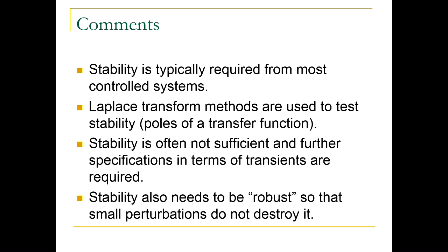If you turn it on now and then you have to wait for 2 years for it to converge, it's not good. If you find that the temperature overshoots, you say, I want to go to 18 degrees, but it goes to 200 before it converges to 18, that's no good. If it converges to a point that is close to 18 degrees, but maybe too far, then that's not good either. So there are lots of features of the transients that will affect the performance of your system.